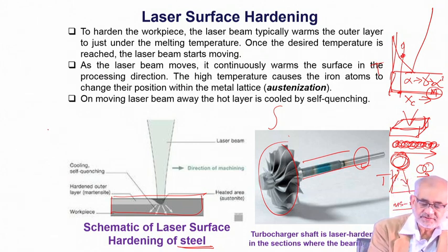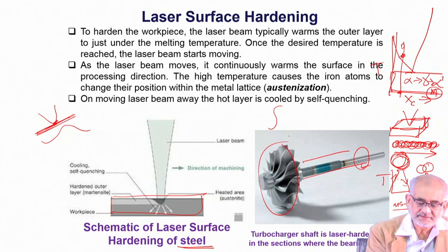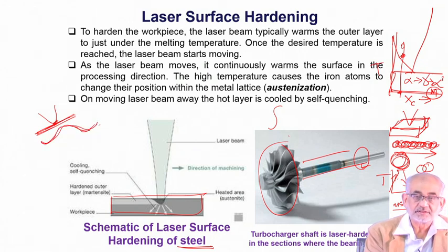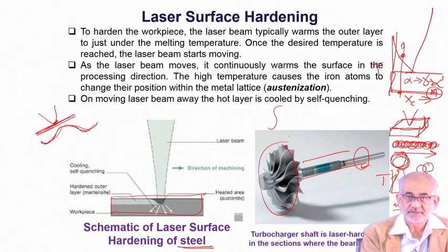The advantage of using laser is that if this is the surface we are talking about, and if I know this is my beam diameter, I can make sure that the beam diameter at the surface is always in focus. And if required, instead of flat, if we are dealing with a curved surface, I'll have to trace exactly this contour of the surface using a computer aided mechanism, controlling the beam.